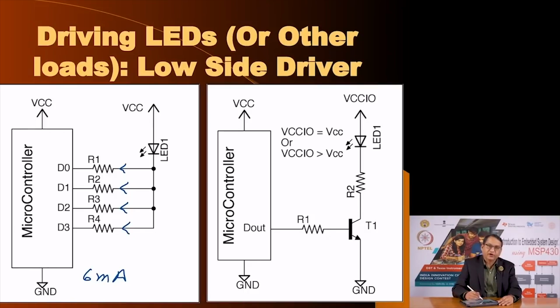Of course, it requires 4 resistors, and the value of the resistor will be calculated assuming that you want 5 milliamperes, and so if we go back here, we can see the calculation. Well, no, the configuration is this one, and so here we have 330 ohm.